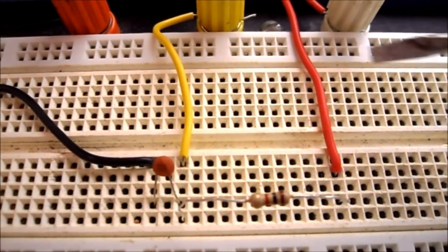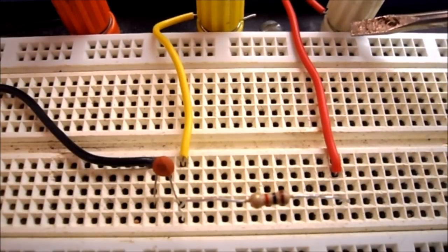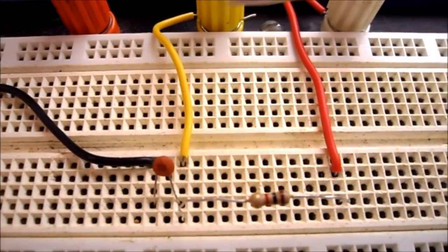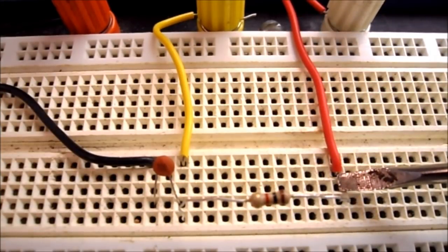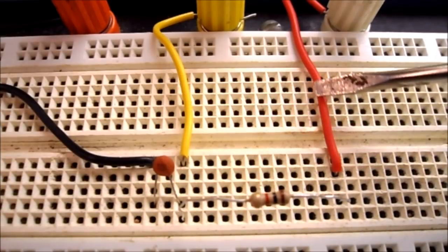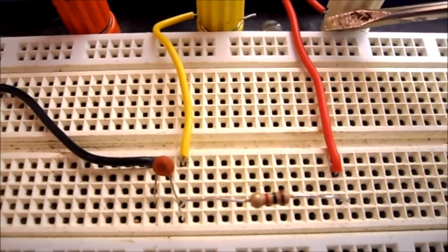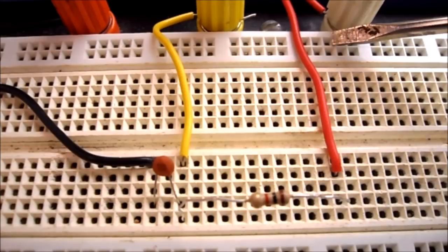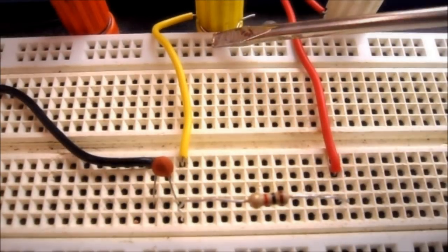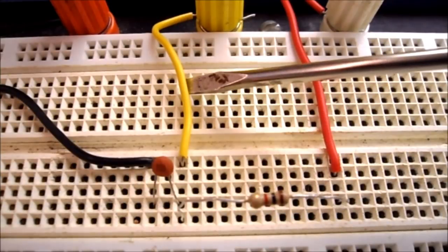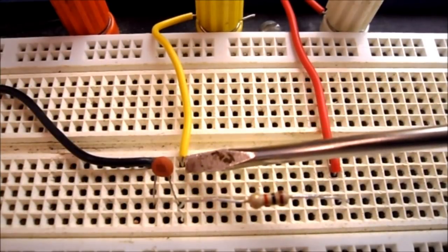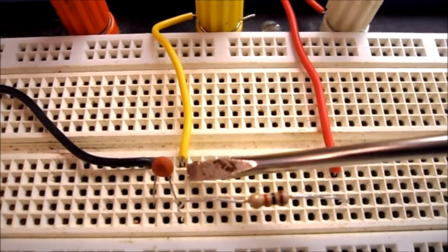So this is my circuit wired up on the trainer, and I've decided to use 3 binding posts. The white binding post with the red lead coming off of it goes to the 1K ohm resistor, and that's where I'm going to plug in the function generator and channel 1 of the oscilloscope. The yellow terminal, which has this yellow wire connected to it, runs out to the midpoint of the capacitor and the resistor.